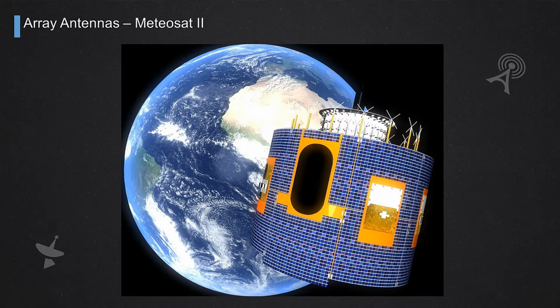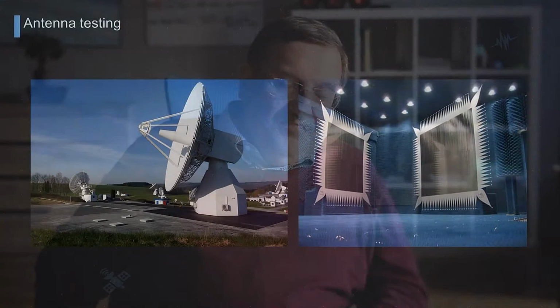And being spinning satellites, so they rotate around one axis, the antennas in this case are used to counter spin. They are so-called despun antennas, so antennas that create a beam that is rotated to compensate for the rotation of the satellite, and they keep being pointed always toward the Earth, while the satellite itself rotates on an axis. Without this array of elements, the beam itself would rotate solidly with the satellite. It would not guarantee the fixed coverage over the Earth.